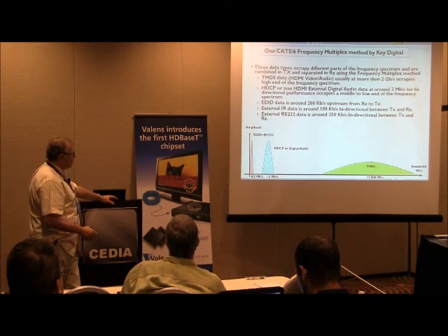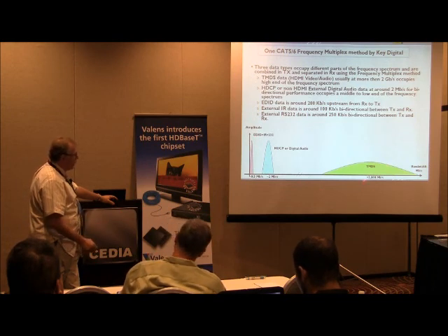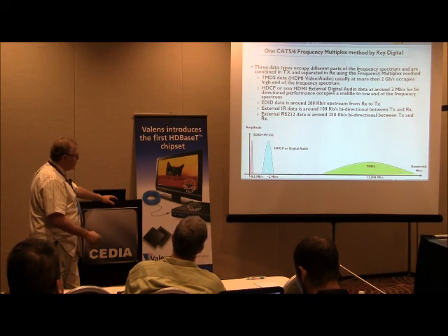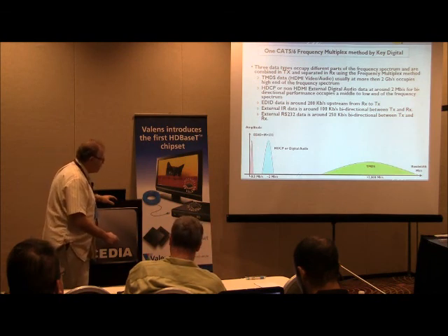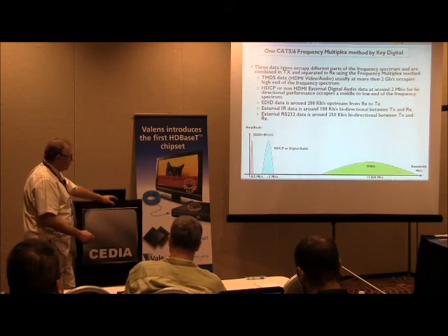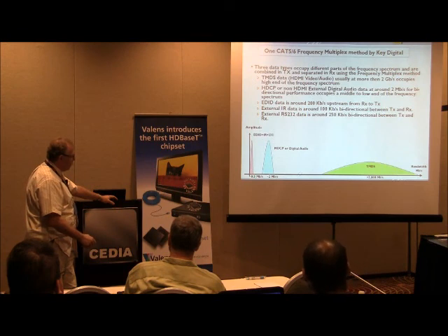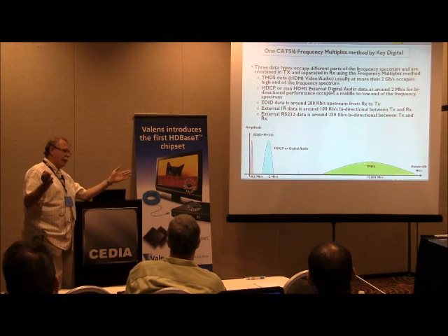What we do is, since TMDS data is essentially high frequency data, it occupies a specific bandwidth in frequency space, which is a very high bandwidth. And on the same lines, we have available spaces in the low frequency where we add HDCP, EDID, IR and 232 data. So we sort of create, in a way, a frequency plan.